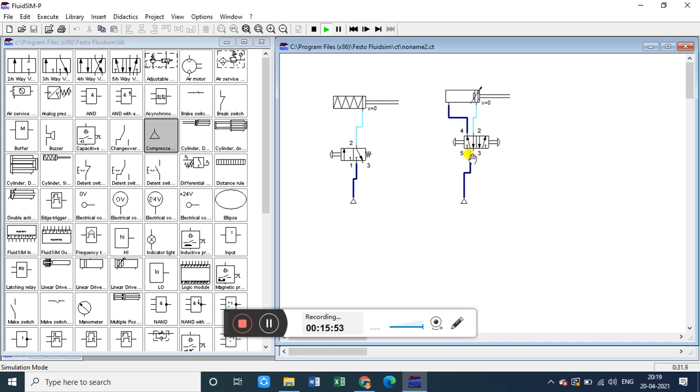Now the external connections will remain as they are, and there will be a change in the valve position or the block position. Because of the application of force from the left hand side, the blocks inside the casing of the valve have slid to the right hand side, and because of that the left side block is in line with the outer connections.